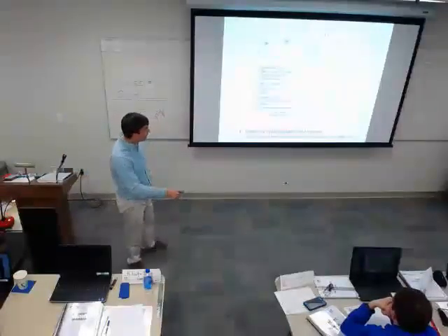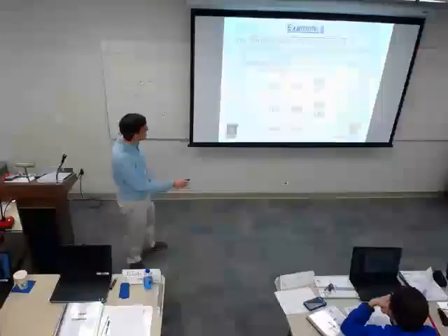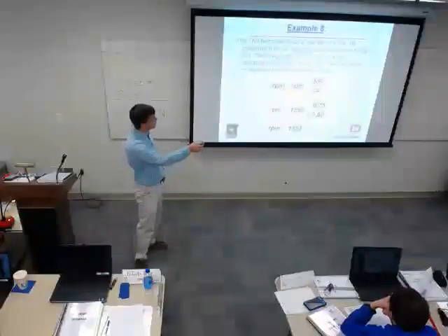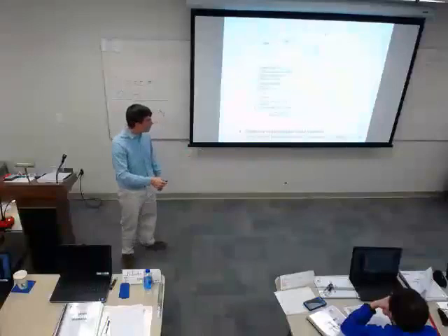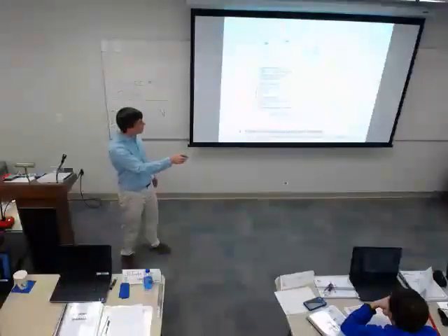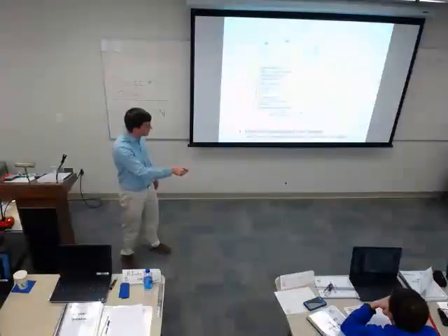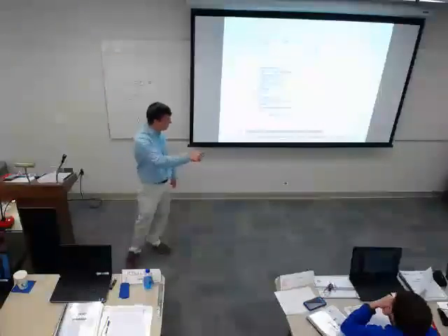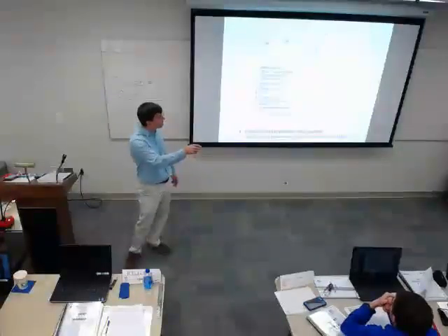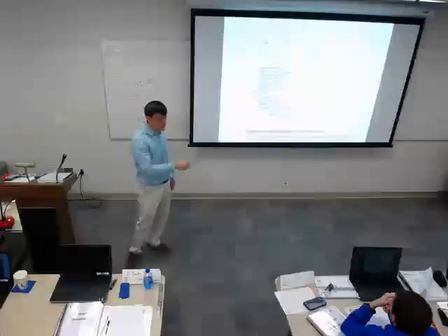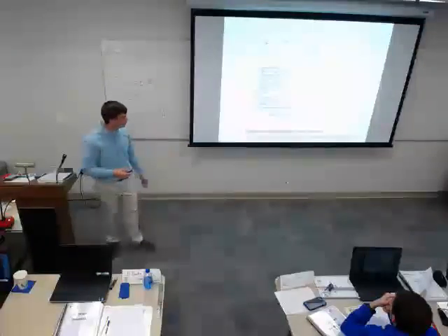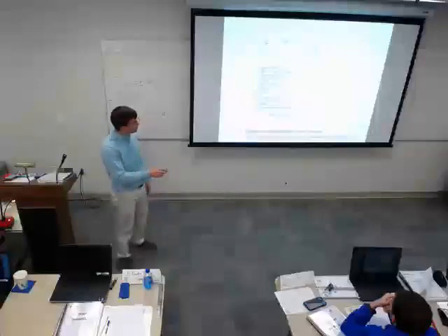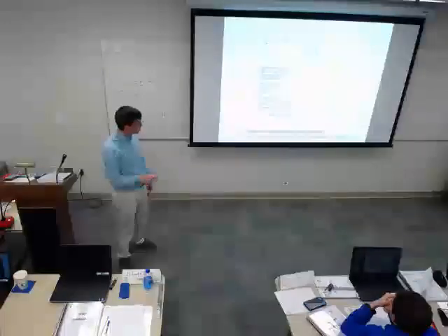Another talking point on this slide: like we were saying in this example, I measured 0.6 and I need 0.75. So if I've got my air handler and my duct system and I go out to this farthest VAV box, I need enough static pressure to get the air through this box. I might have to increase my fan speed to do that. I need more pressure generated at this point.